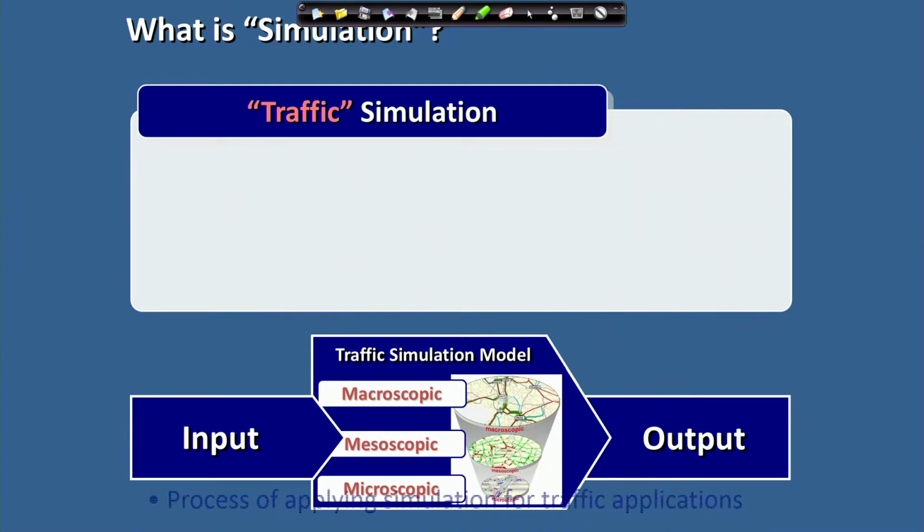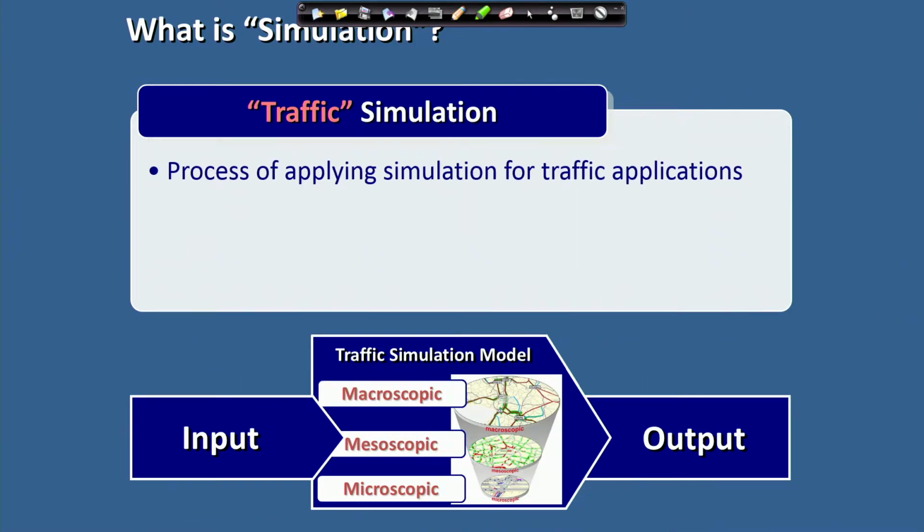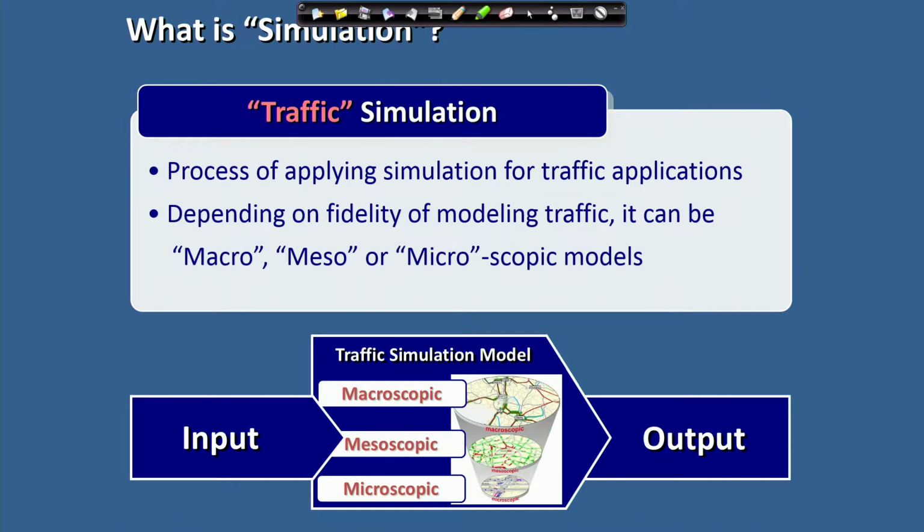Coming to traffic simulation, the same thing applies as for other traffic applications. There are different traffic simulations, and we usually define them based on the so-called fidelity of modeling of traffic. The fidelity means how detailed we model the simulation. So we have micro, meso, and macro.